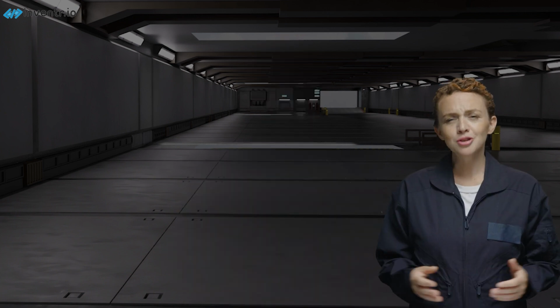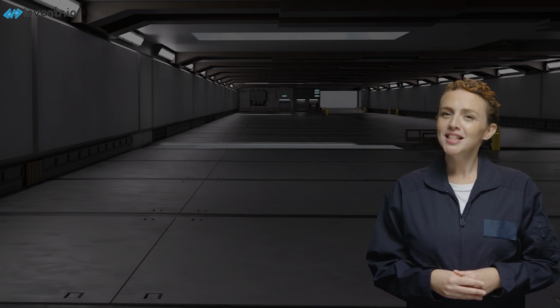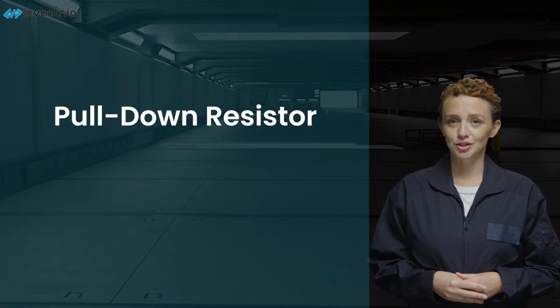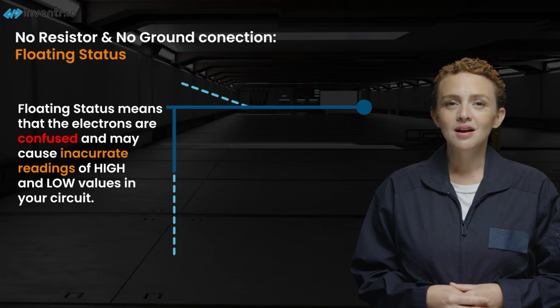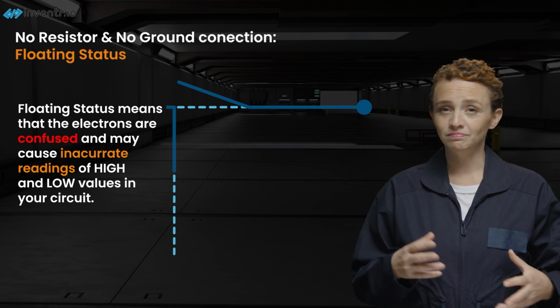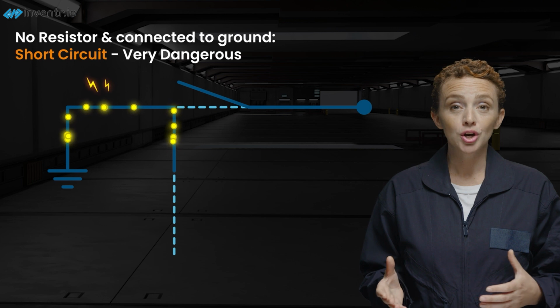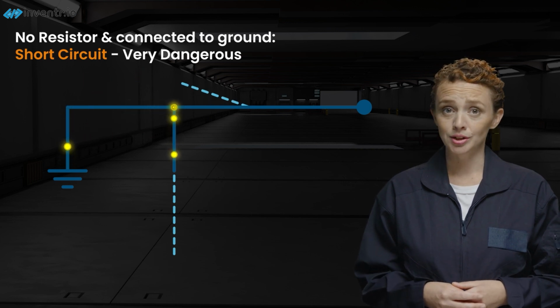Moving on, the extra resistor. A keen observer, aren't you, Explorer? You see, the extra resistor we're talking about is what we call a pull-down resistor. Its job is to make sure our circuit behaves properly when the switch is off. Without it, our switch being in the off position could cause our circuit to get all wonky. Imagine it like a crowd of electricity not knowing where to go and causing a ruckus. We certainly don't need more chaos around here.